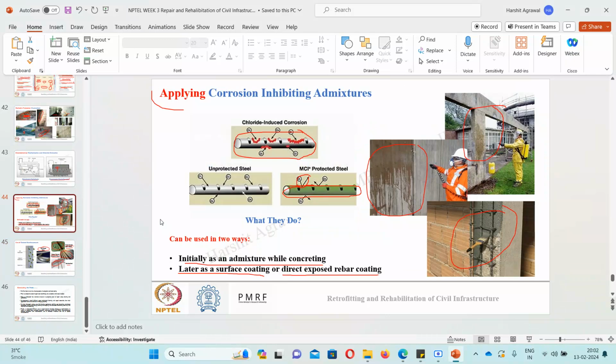Normally water is penetrating through the parapet or the outside of the wall, and it is going through the porous concrete. And actually what is happening is that the conduit pipe does not have proper adhesiveness with the concrete, so through that porous media it is going and getting stagnated in the ceiling fan areas, and through that the leakage is coming.